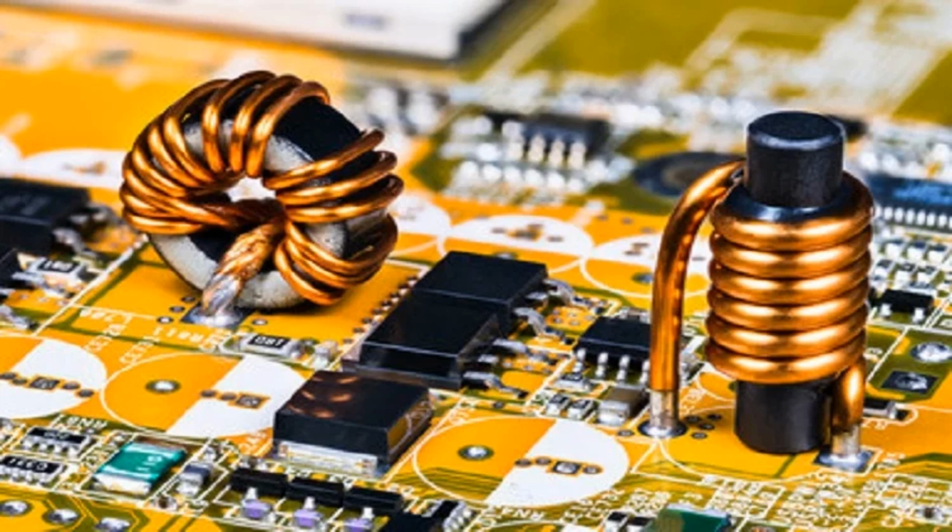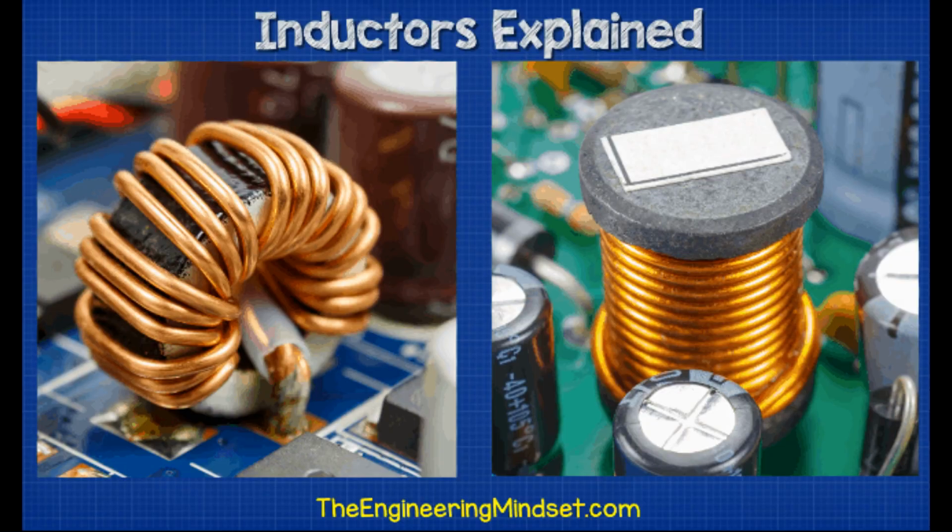Proximity sensors. Application: Inductive proximity sensors are used in industrial automation to detect the presence or absence of metal objects. These sensors are commonly used for position detection, counting, and as limit switches in machinery. Example: Inductive proximity sensors are often found in conveyor systems to detect the presence of metal parts for sorting or quality control.